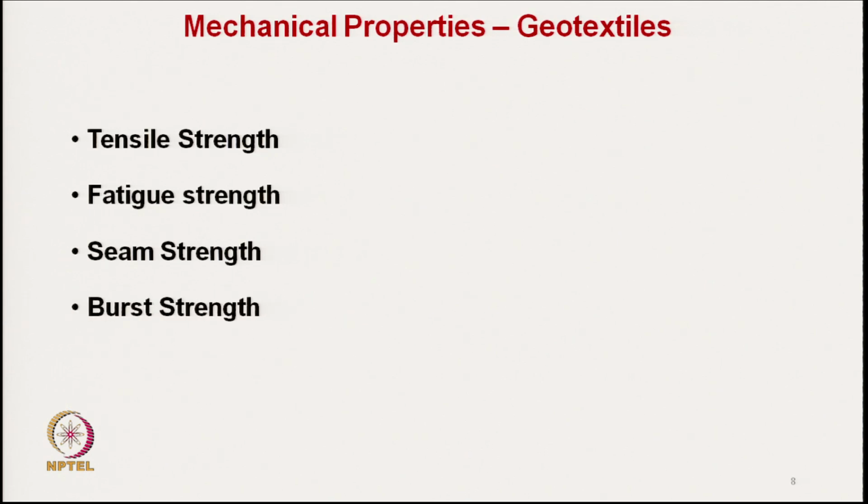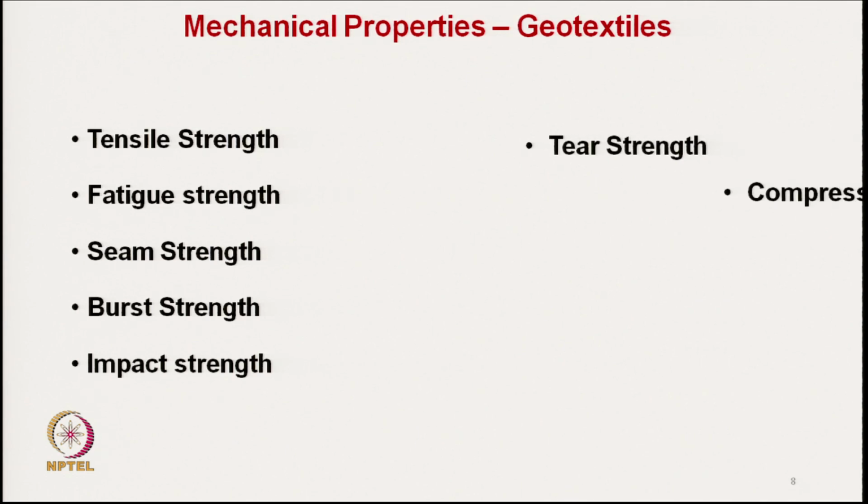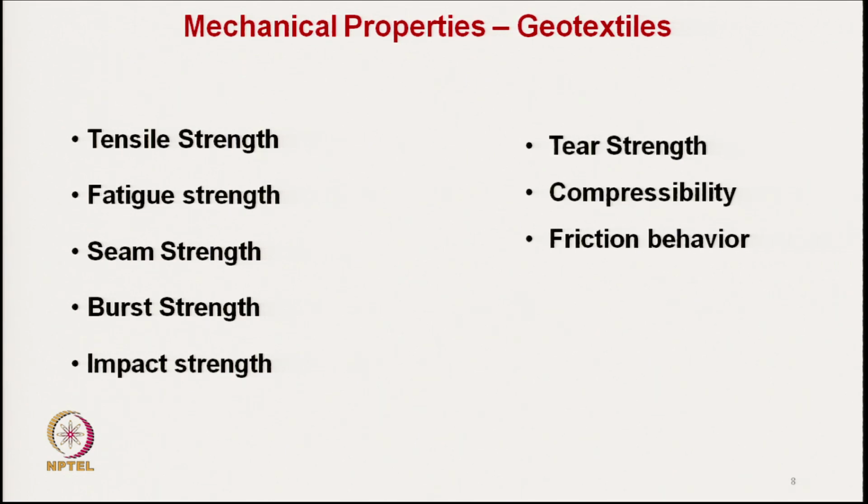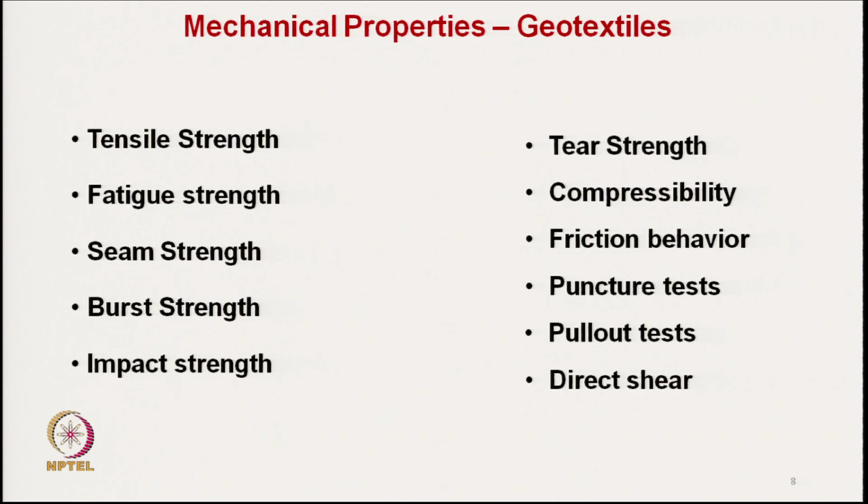Now, coming to mechanical properties, there are a large number of properties we can test: tensile strength, fatigue strength, seam strength, burst strength, impact strength, tear strength, compressibility, frictional behavior, puncture test, pull out test, direct shear test. These are the tests we must perform to get a clear picture about the performance of geotextiles. So, we will discuss them one by one.